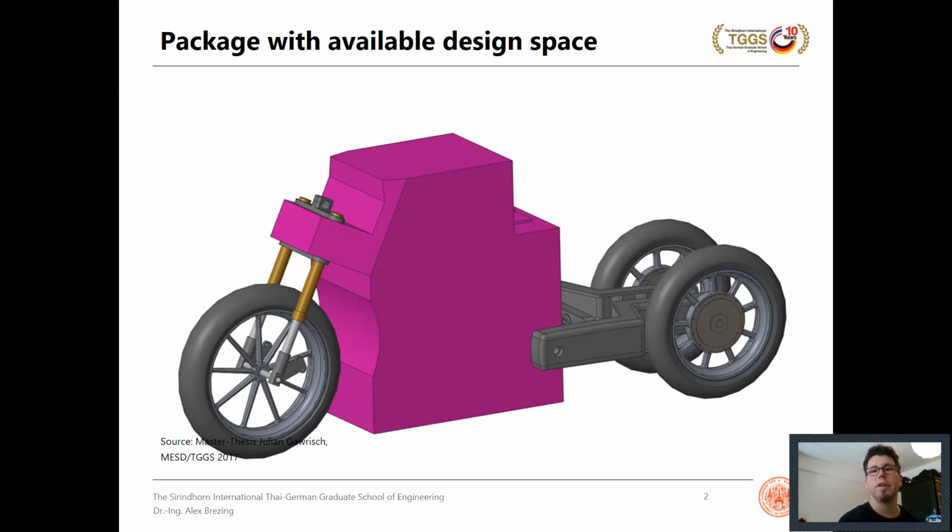There's one sitting basically over the 2 rear wheels, and it's an electric vehicle, so we don't have an engine. We only have the motors in the wheels, but we do have quite a big battery pack. And of course, we need to create a frame structure. And because it's very different from established vehicles, we try to get an idea what an ideal structure is. So the battery pack basically is in the lower front region, more or less right behind the front wheel.